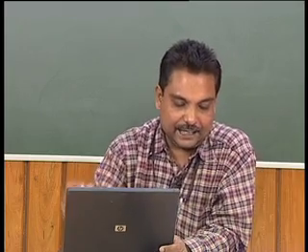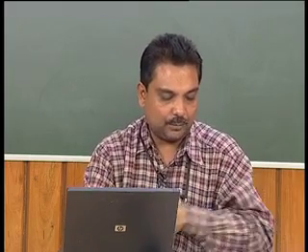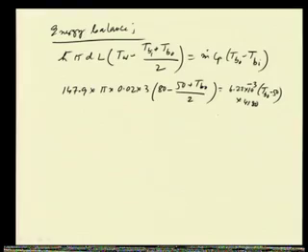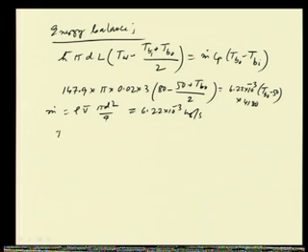This m dot is the mass flow rate that can be calculated as pi d square by 4 into V bar into rho. So, m dot is rho V bar into pi d square by 4, and that value is 6.22 into 10 to the power minus 3 kg per second. Then from these previous relations, we can find out T_bO as 60.5 degree centigrade.